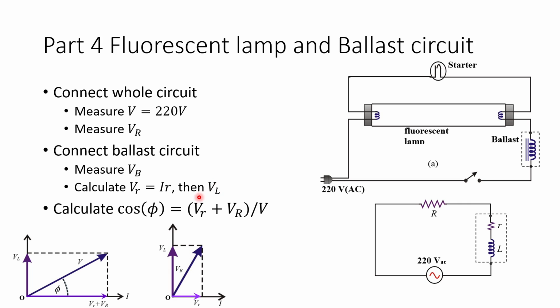Once you know VL, then you can calculate the power factor from either VL or VR, or both. Either way, you can calculate the power factor and calculate the actual power that goes into the circuit.